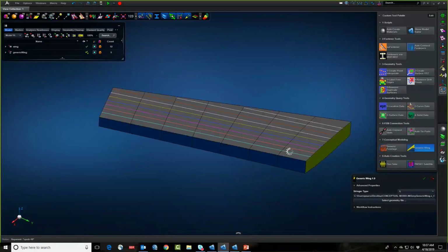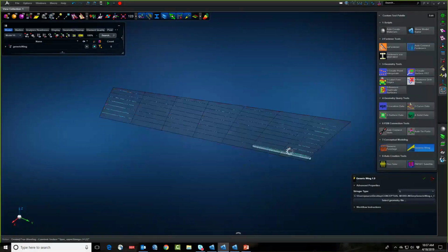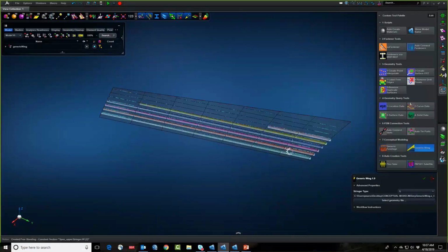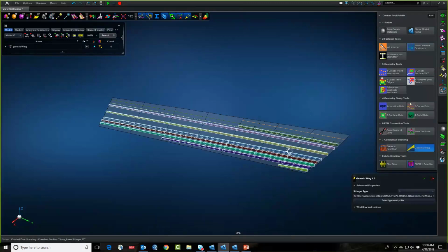And what my script is doing is it's locating the stringers, it's locating the ribs, it's locating all the different pieces of geometry. For the stringers, I'm actually creating beam elements. So here you see those beam elements being created. And not only are they beam elements, but they're tapered. So it tapers from the fuselage out to the tip of the wing, and that was just my decision. You could do whatever is your structure. I just chose to do that for mine.